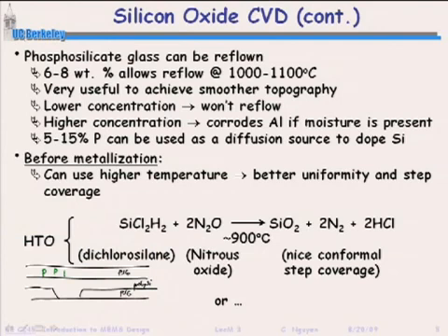It will diffuse into the silicon, and it'll diffuse in a way that's very uniform, right, from the top and bottom. And so you get a very well-doped mechanical layer between the phosphorus if you take this up to high temperature. So that's what I mean by this right here, that this can be used as a diffusion source to dope silicon, and that's used quite often in MEMS technology.